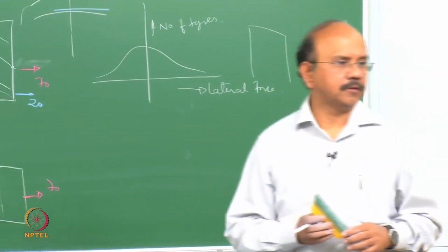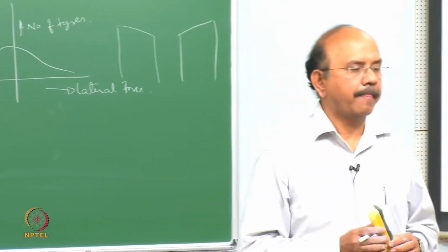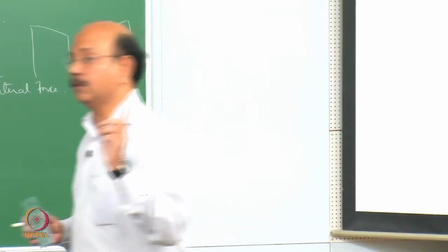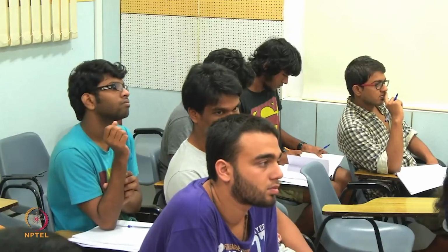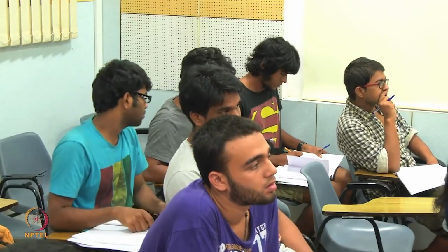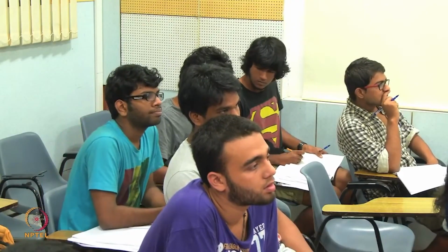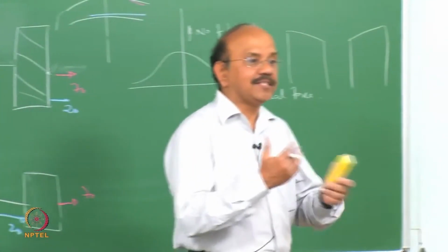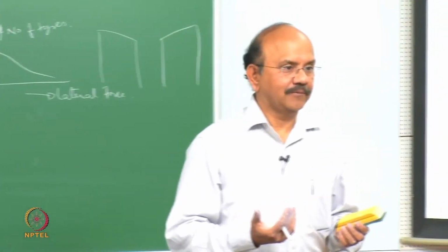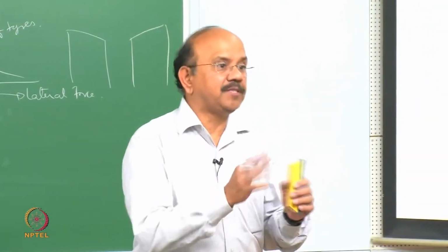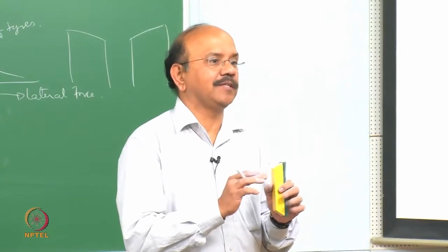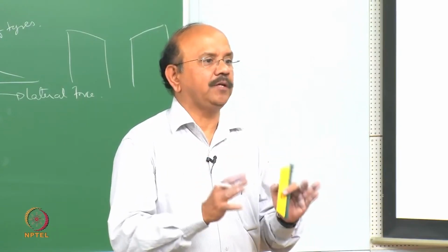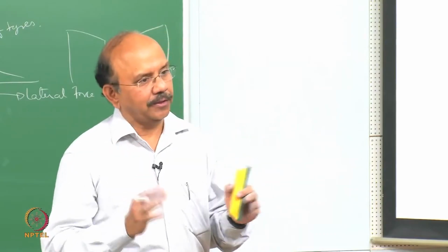Okay, now, yes. Conicity is also called camber? No, camber is from the vehicle. Conicity is from the tire. The tire becomes a cone. So the reason is not the same. The deformations may be similar, but the reason is not the same. When we say camber thrust, it is coming from the vehicle where I give a particular camber.